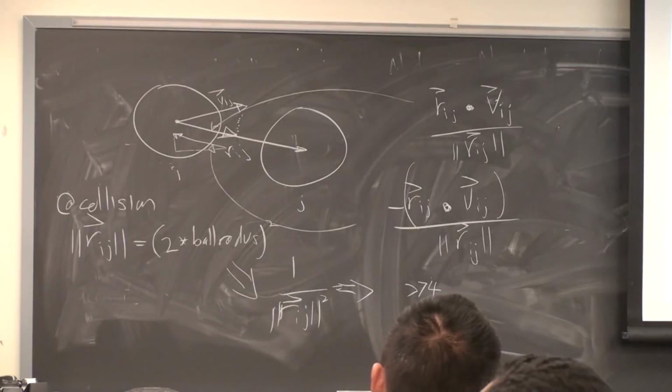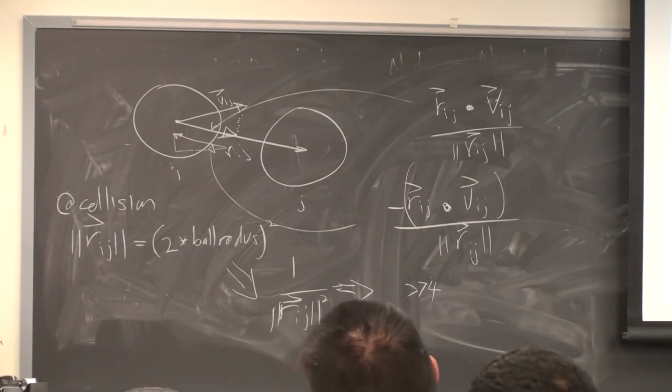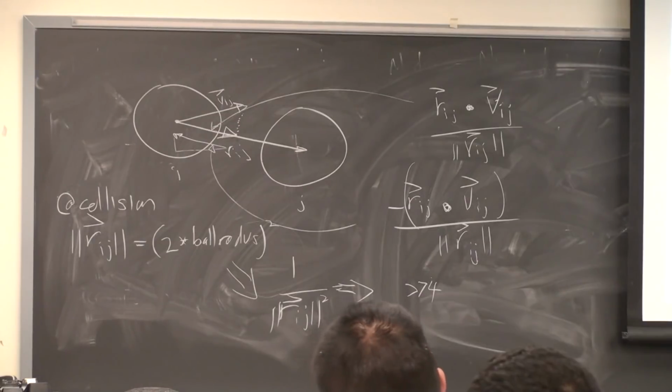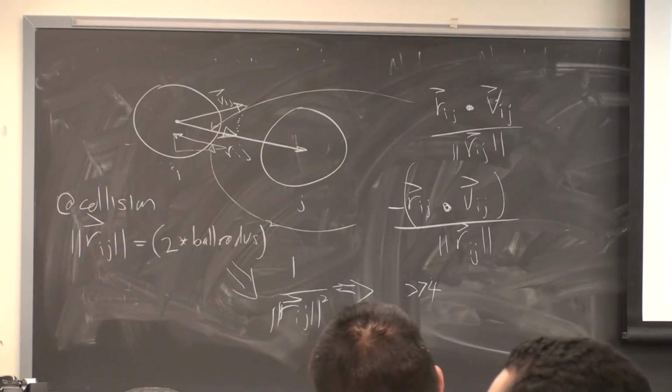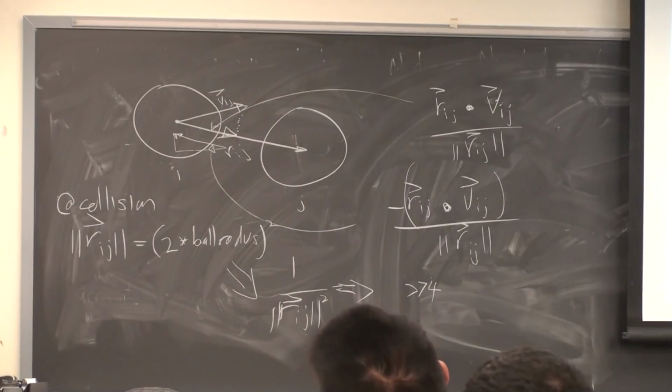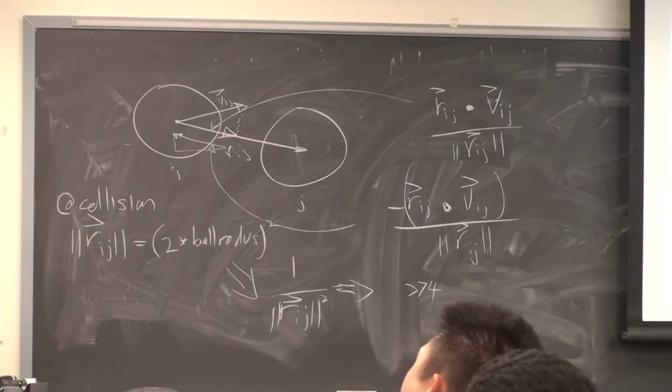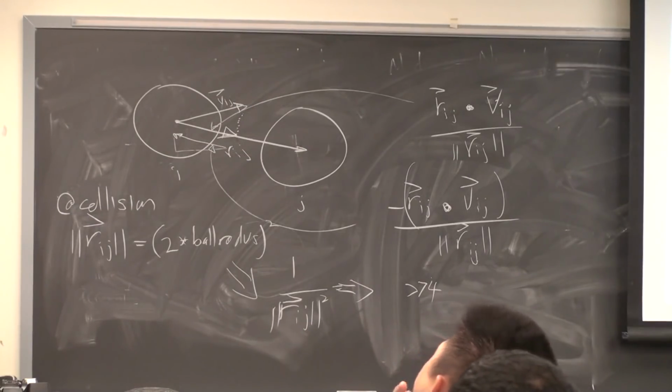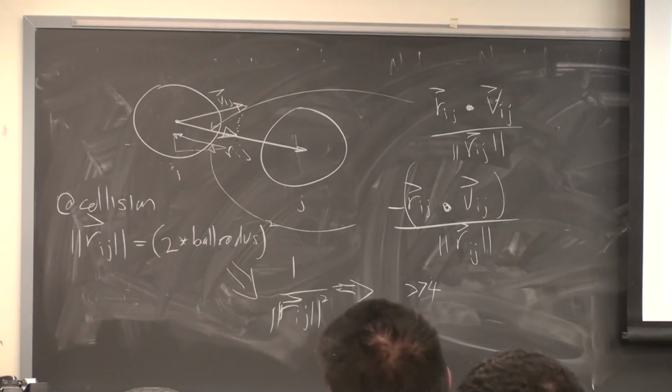So the two big chunks of this are the dynamics and animation of the balls, and direct memory access control of the sound. I'll give you a lot more information on that. I have a bunch of examples on that. There's another small detail, and that is that the serial peripheral interface has to be set up in a very certain way called framed SPI. And I have some examples on how to do that also. So you're going to have to get down into the lower level stuff just a little bit to make this go.